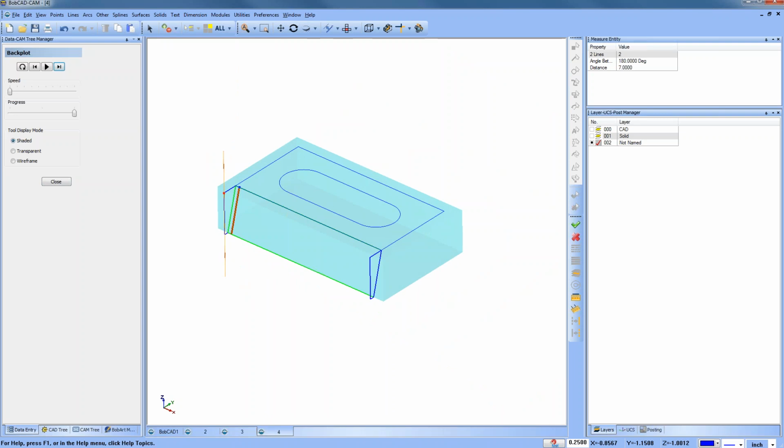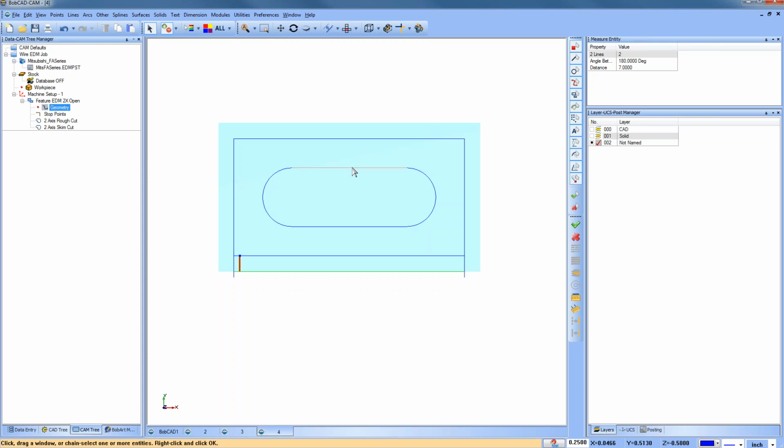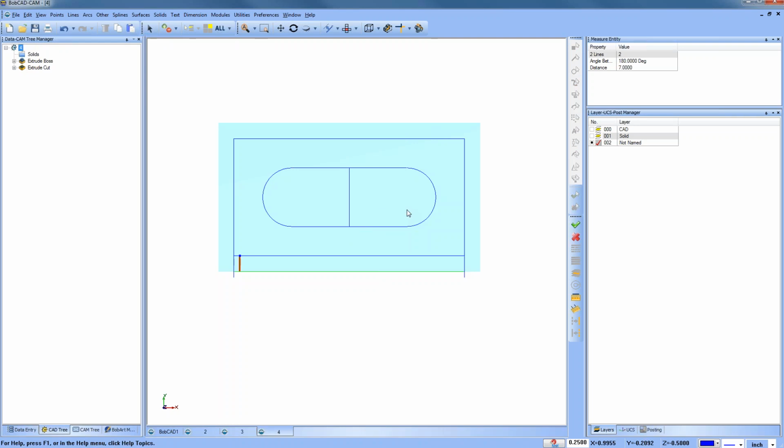Okay. So we talked about straight cutting, taper cutting, land and taper, cordless, rough cut, tab cut, skim cut. We went through all of that. We're running through a lot of time. I still have all the really cool 4-axis stuff and simulation stuff to get into as well. So we talked about tabs. One good question that came up was multiple tabs. One of the answers that I gave on that was to use an open profile. So what we might do here is, maybe if we wanted 2 tabs within the shape, and depending on the geometry that you get into, sometimes it can get pretty complicated, especially in the 4-axis.